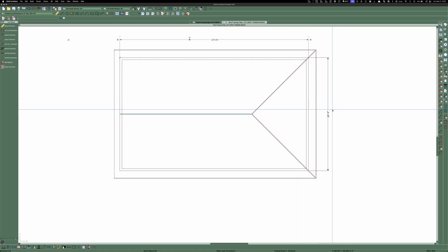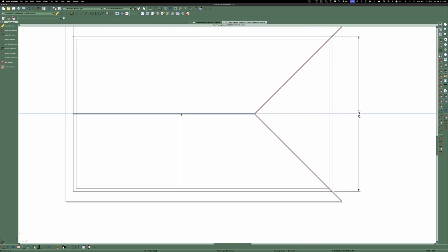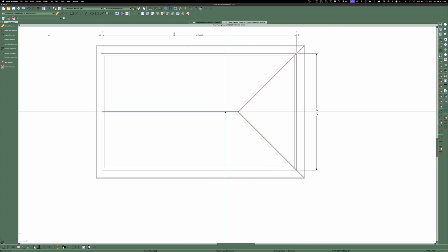But anyway, so here's your 24 feet. What you do is you take 24 minus the ridge thickness. So this could be a big structural ridge, 3.5, 5.5 wide, whatever. You take the span minus the thickness of this ridge, which happens to be 1.5 inches.